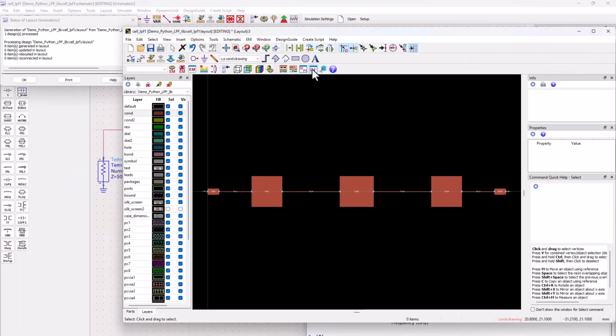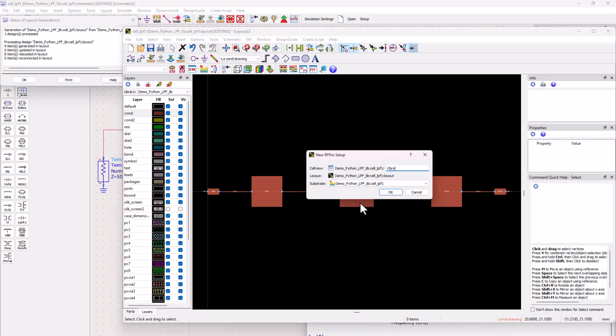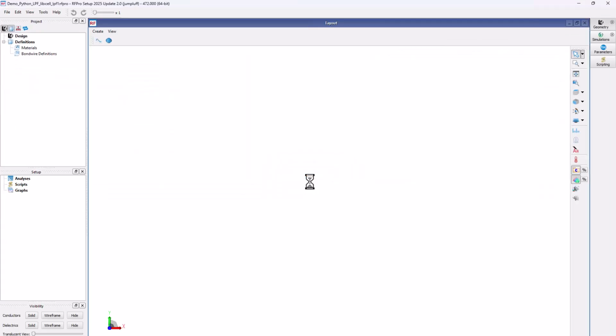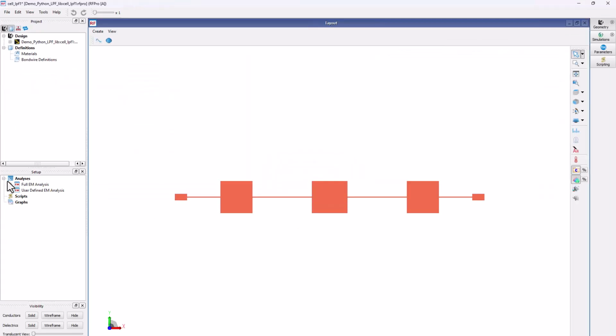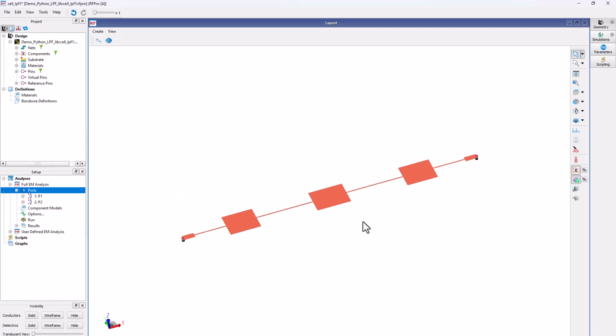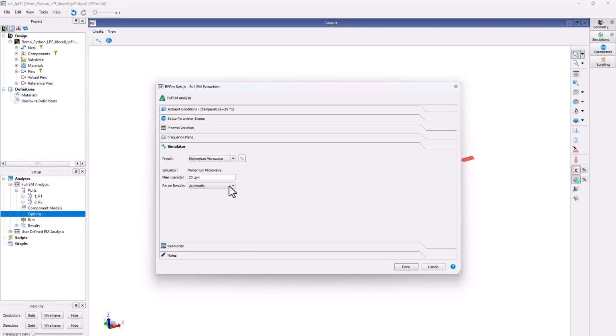So I can go ahead and switch on RF Pro, select that cell LPF1 dielectric, click OK. And now we have our circuit in RF Pro. And now if you want, you can perform momentum simulation, you can perform FEM simulation and so on. So let me quickly add those pins to create 2 ports, as you can see at input and output. In the options, I will go ahead and simulate it till 5.5 gigahertz, now from DC to 5.5.